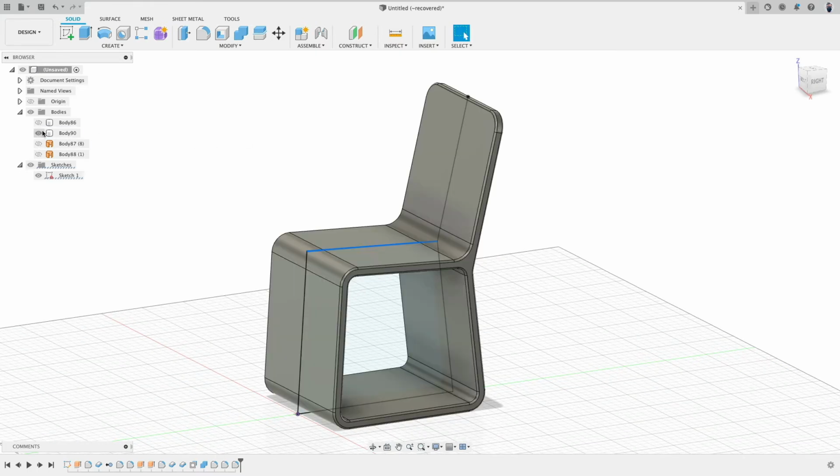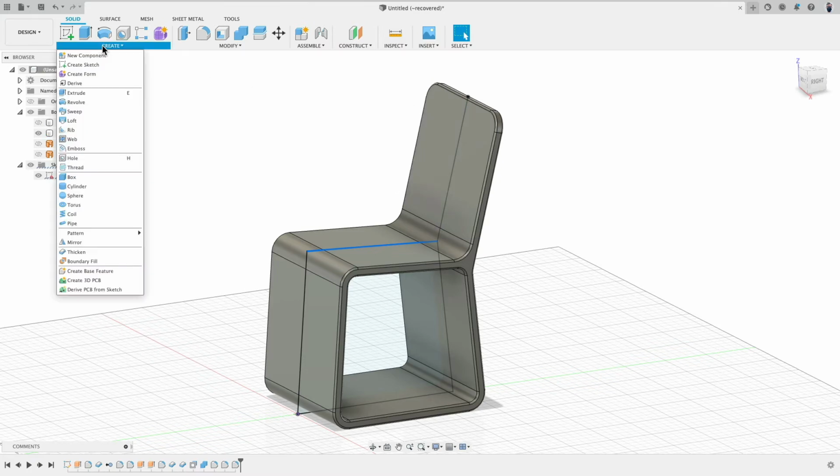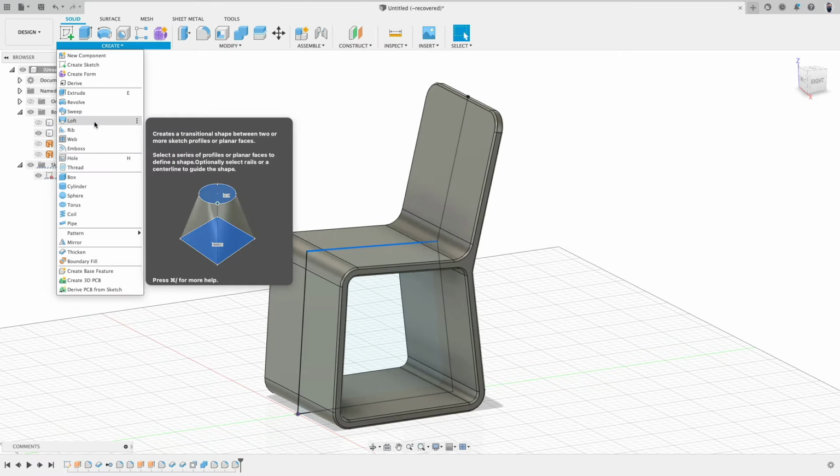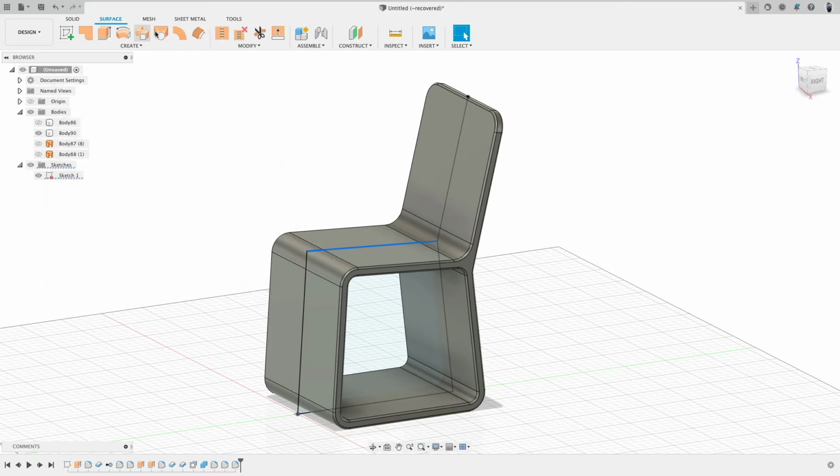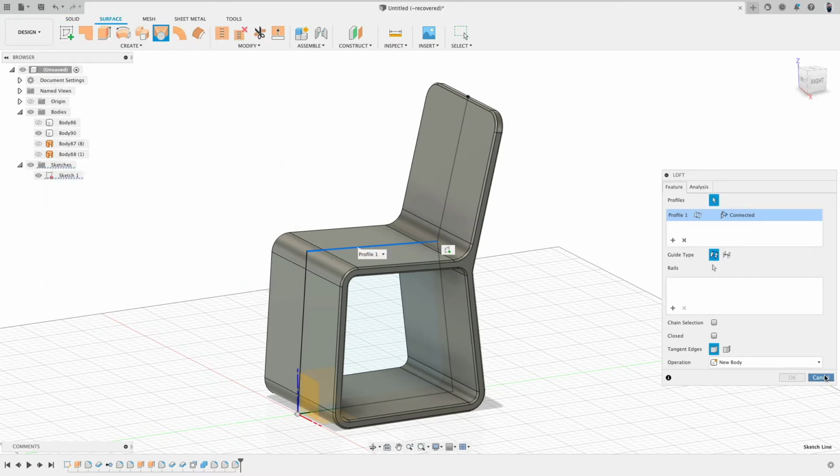But if we would like to bend this area, we need to have a sketch on the outside, the inside, and the outside. So we blend between those 3 sets. And that is what the loft command will do. As you can see in the image, it lofts between 2 different shapes. We also have loft and surface, pretty much the same.